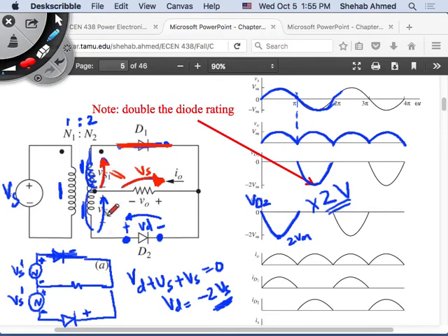Okay, and then here, same thing. This is my supply voltage, and then this is an open circuit, and I would like to find the voltage here. So I go around a loop. This is my loop here. I add the voltages that are in the same polarity, and the sum of the voltages around the loop is equal to 0. So this voltage was Vd, this voltage was Vs, and then this is V output, but it's also equal to Vs here. So I just put Vs instead. Okay.